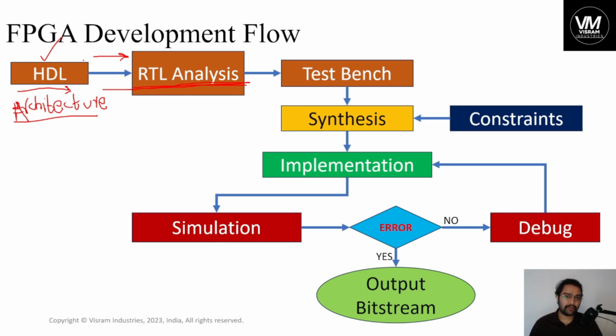if you don't end, so if there are any such errors in the HDL script that you have made, and if it is not compatible with the hardware architecture of the board that you have selected in the EDA environment, in the RTL analysis you will find all the issues, and you can rectify them by embedding a test bench to the HDL. A test bench is again a file which is made for verifying and rectifying the errors in the HDL using test bench simulation.